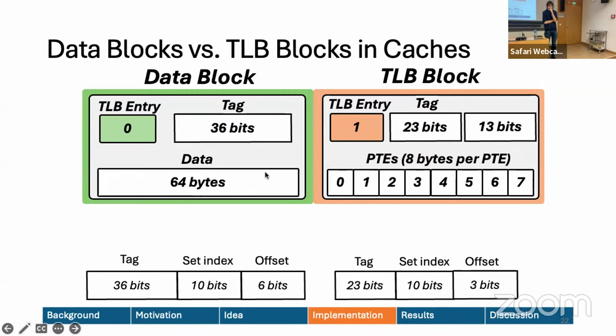The second scenario, which is very rare, and I'm not sure if it's possible in processors right now, is a coherence eviction. But not even in this case, because we do not store it in the LLC, in the directory. These are opportunistic data. So you do not care about invalidations, for example. If you invalidate the cache line that the data is pointed by, then it doesn't matter.